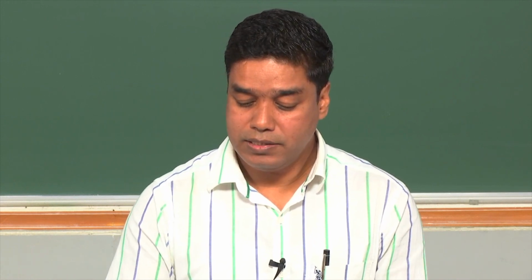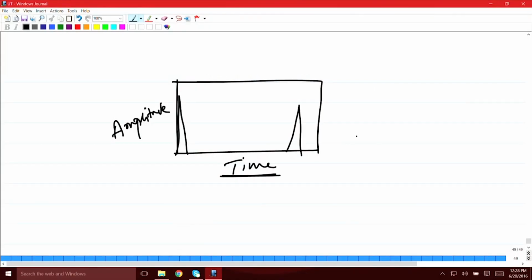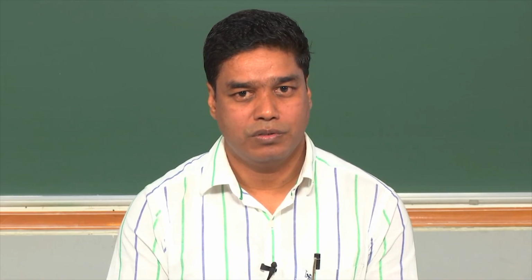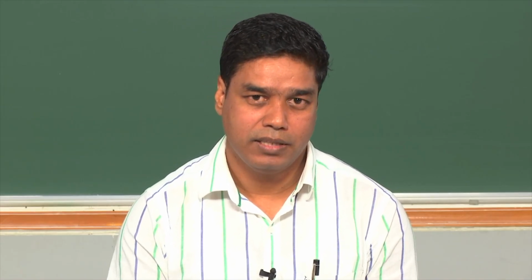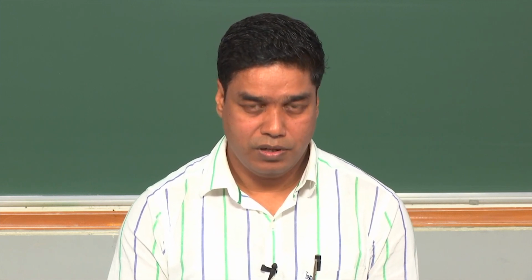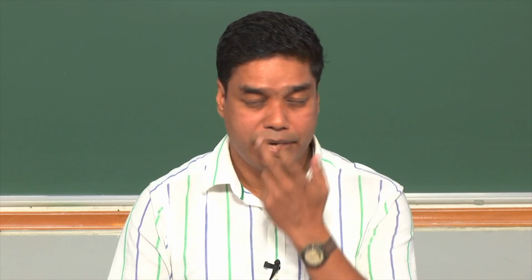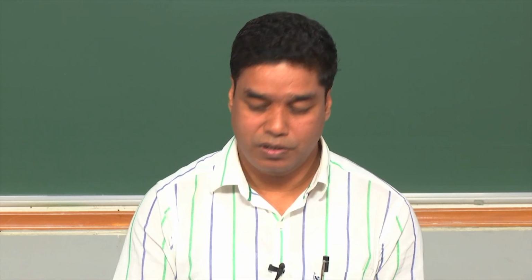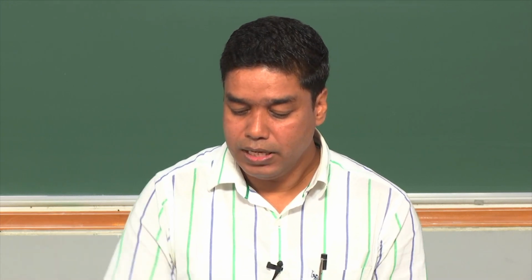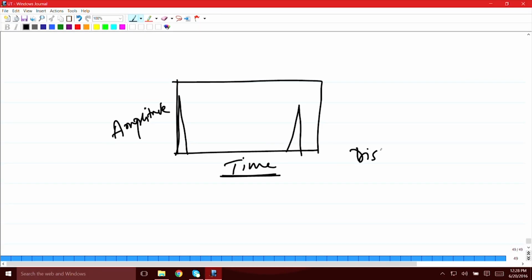So, this time can be converted into distance if you know the velocity of sound wave in the material which is being tested. And most of the time it is known, because in most of the common metals, alloys and many other materials, the velocity of sound is known. So, if you provide the velocity of sound, this time can be converted into distance, because distance is velocity into time.